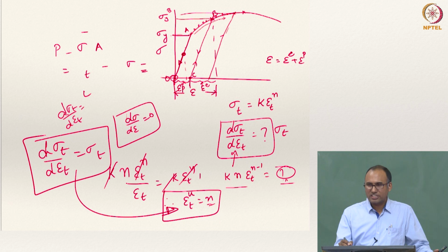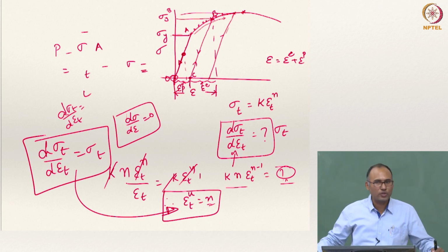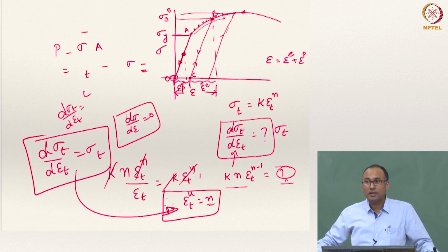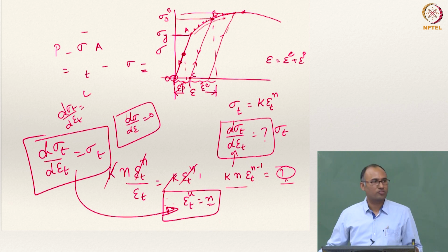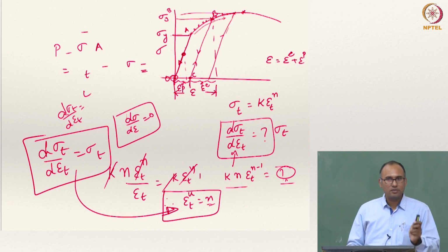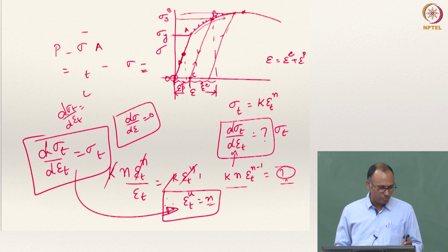And if you have loaded just before the necking, then you will see that suddenly the material fails without giving you any sign, right? So a material which is ductile to begin with could actually be hardened significantly just by plastic deformation. Yeah. So that is a very important thing to realize when you are looking at mechanical deformation of materials. Okay. So with that I will stop, and in tomorrow's class we will discuss the measurement of the remaining mechanical properties.